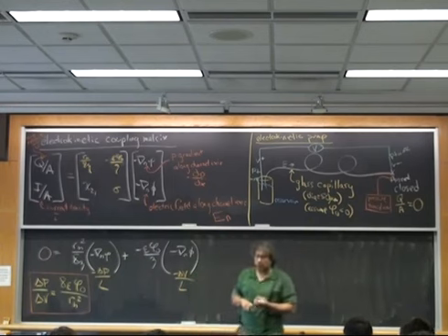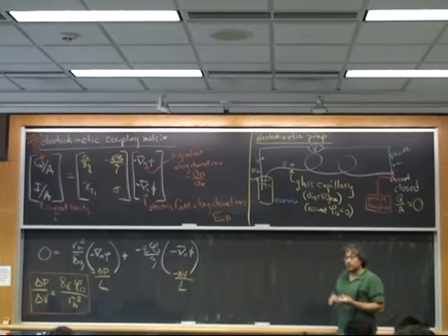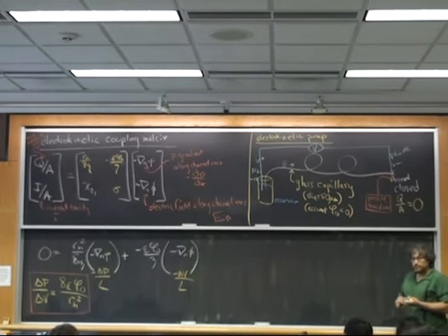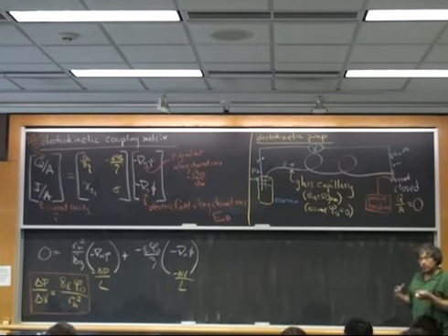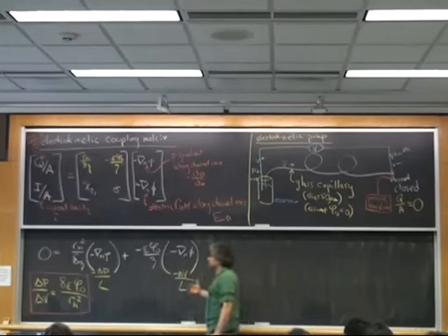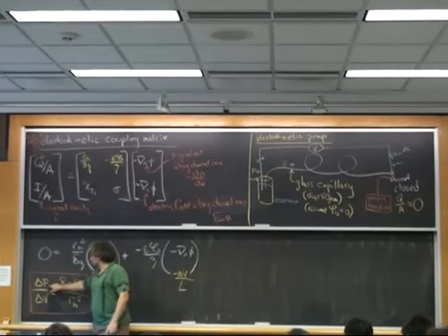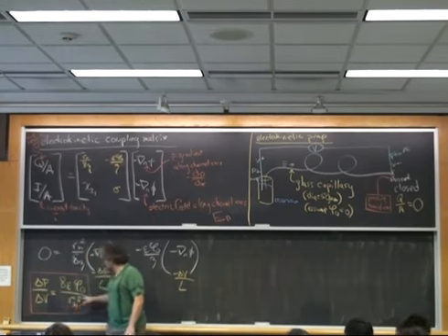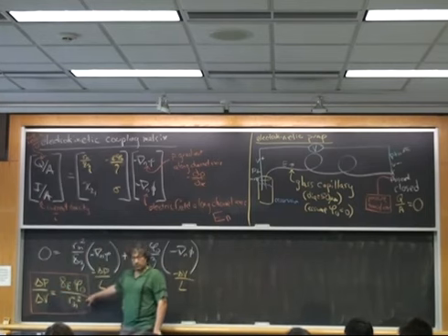I said the surface-driven flow doesn't scale with the characteristic length, but the Poiseuille flow scales with the length squared. Now if I ask Couette flow and Poiseuille flow to be in equilibrium, if I say they're going to generate the same flow rates, then the only way for that to happen is for me to have a pressure whose magnitude relative to the voltage is also scaling with this radius squared, right?